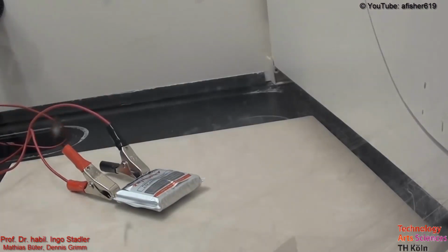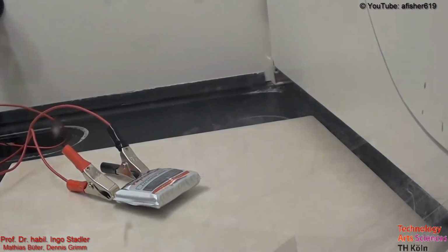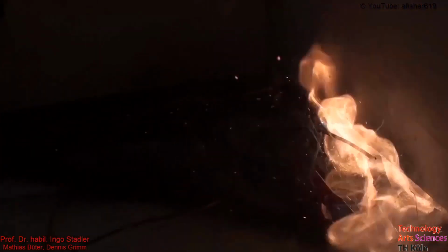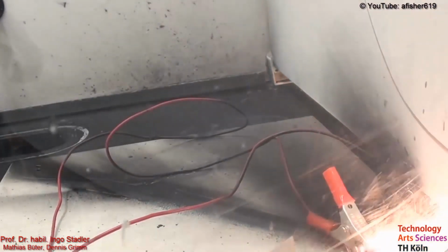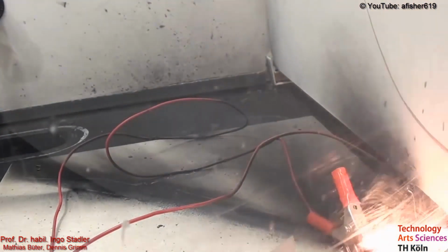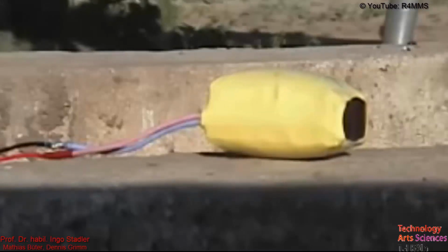An important aspect with lithium-ion batteries is the safety aspect. When a cell is short-circuited, overloaded or has a too high temperature, an exothermal reaction is the consequence and the cell materials are decomposed. First, the so-called venting occurs. That means the cell opens and gases are released. The problem here is that the escaping gases together with the oxygen of the air form a flammable gas and the cell is going to burn down.